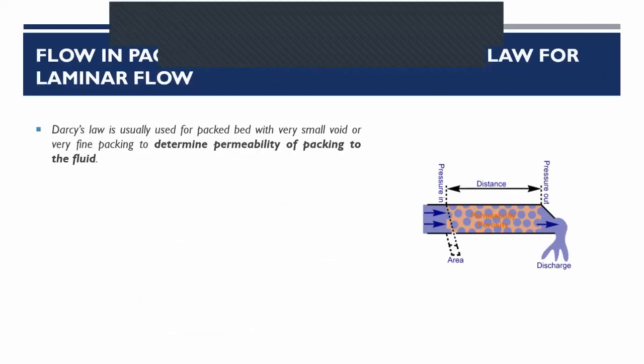Now we go to Darcy's law. Darcy's law is usually used for packed beds with very small voids or very fine packing. The size of the packing is very fine, so it has a very small diameter. Darcy's law is used to determine the permeability of the packing to the fluid.